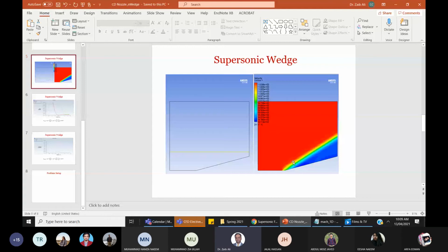Once that line crosses the oblique shock here, you want to calculate the slope of this one. That will be y2 minus y1 over x2 minus x1, or tangent inverse of delta y over delta x. So how to locate what the value should be?